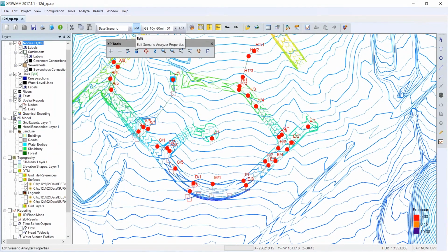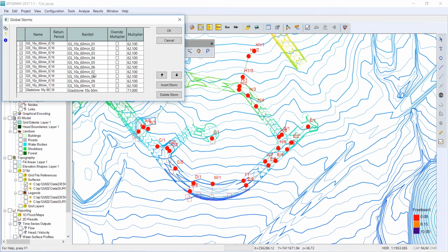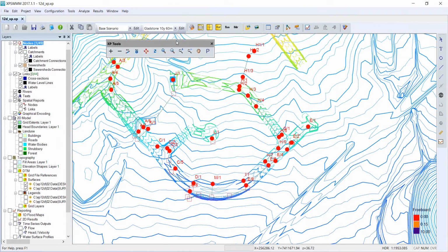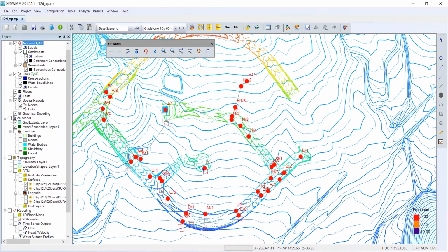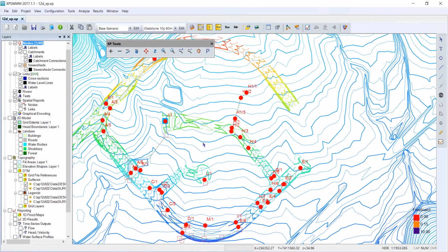If you were doing your real project based on AR&R 2016, you would then run some statistics on your hydrographs and work out the hydrograph that was appropriate for the risk of your project, typically the median, and you would just run that one. So I'm going to follow that process, and I'm just going to turn a single storm on to run the hydraulics. You could always run all those storms through the hydraulics, of course, but for today's presentation, I don't want you guys sitting here for too long waiting for the computer to solve.